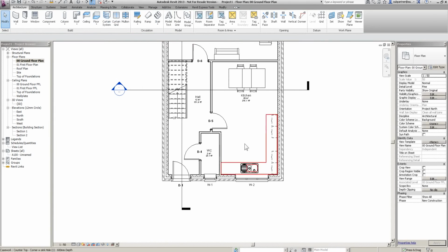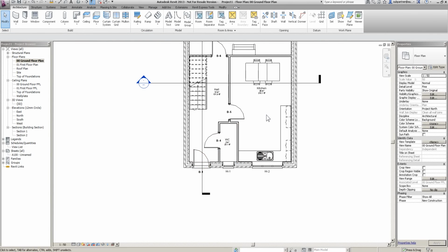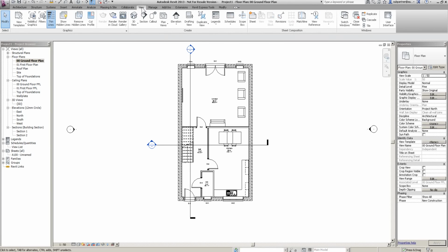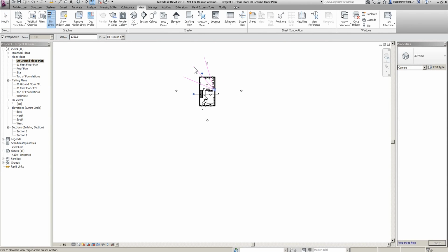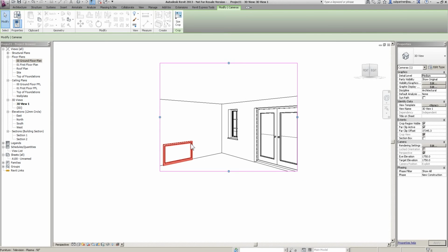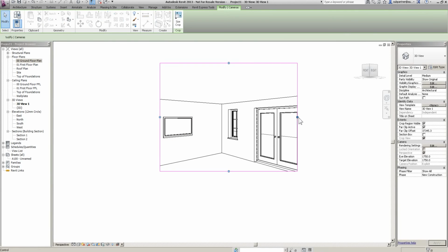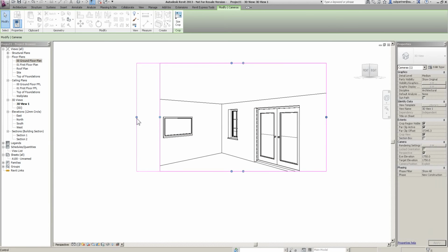Now what I'm going to do is place in here some cameras, because we haven't seen the cameras yet. So I'm going to go to either my quick access toolbar just here, or under your view tab just here, throw a camera in. I'm going to throw a camera in looking outside my building. Always take the focal point beyond the building. There we go. Schoolboy error again. It's on the floor, that's no good. Let's place it up just there. Fantastic. Once the camera's in, let's just drag this. Don't drag it too much because it will obscure it if you're not careful.